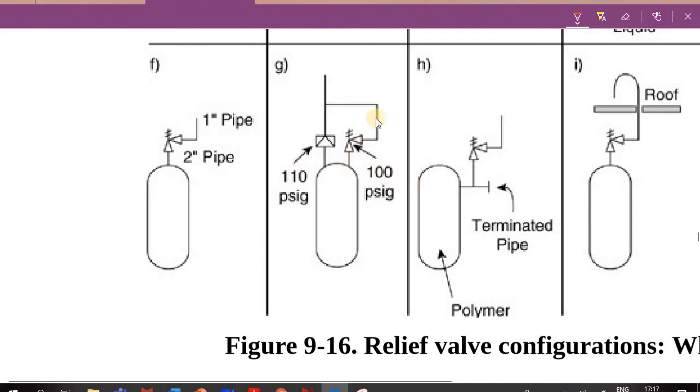Even if this goes back to setup pressure, or goes to 100, it still goes higher while this is open for some time, and this would affect the rupture disc, which may not operate at the correct pressure because they are very close to each other. So this may not be operating at the correct setup pressure.